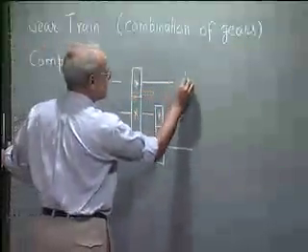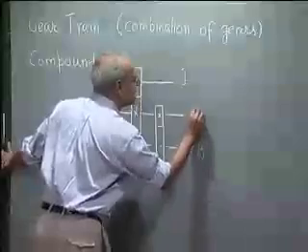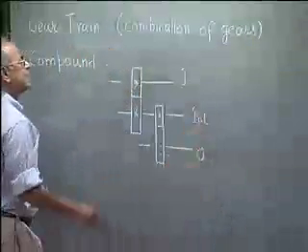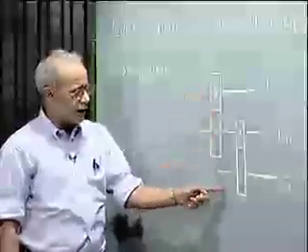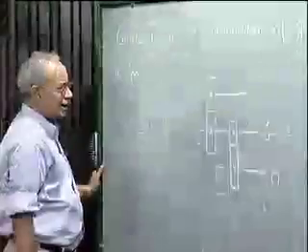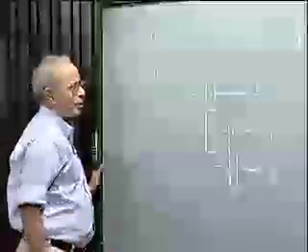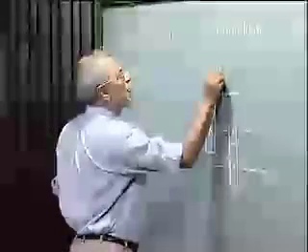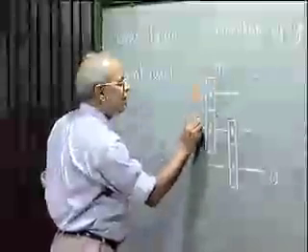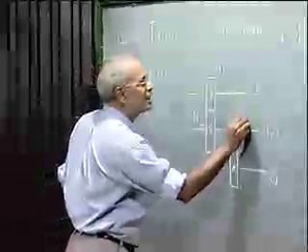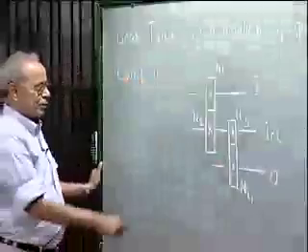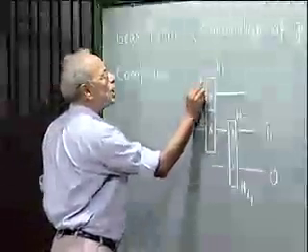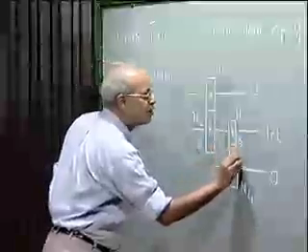this is the input shaft, this is the output shaft, and this is one intermediate. As you see, on this intermediate shaft there are two gears. So this is a compound gear train from here to the output shaft. Now let me find out what is the speed ratio in such a compound gear train. Let the number of teeth be N1, N2, N3, N4, because gear number 1, 2, 3, 4.